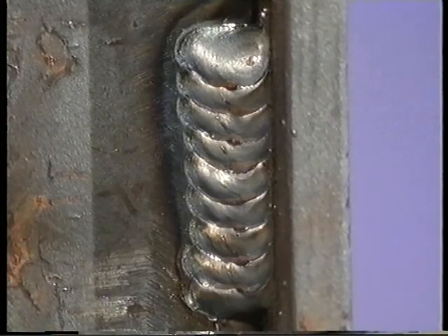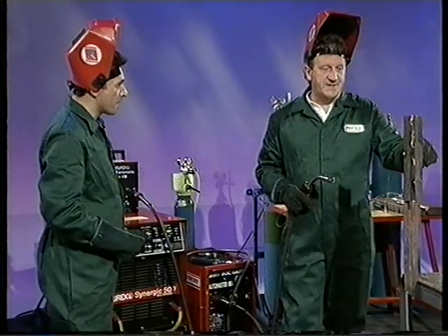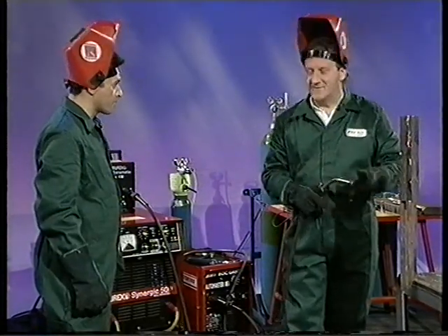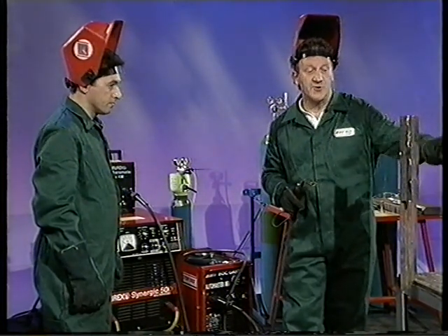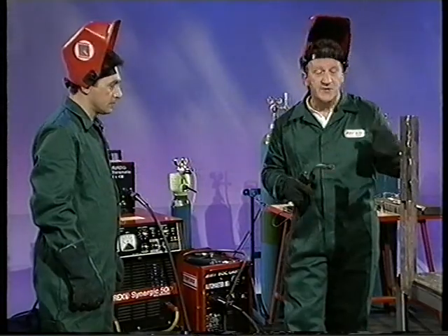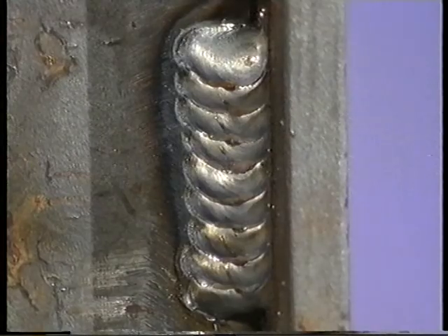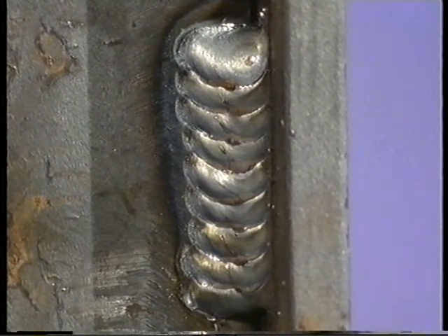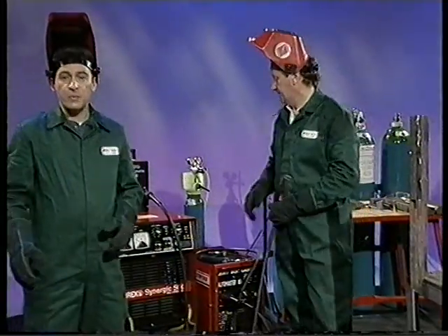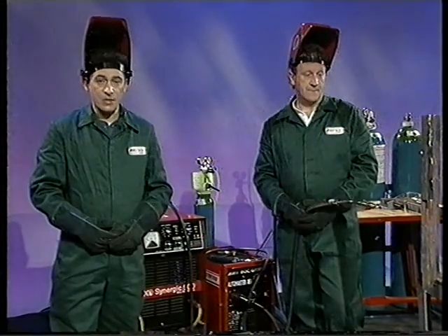Right. Okay, so that's the weld procedure, is it? This is for demonstration only. If we were doing a proper weld procedure, we'd certainly be restraining this by having strong backs on the back. This increases the mechanical strength of the weld. Other ways to increase the mechanical strength are to use flux core wires, for example. Okay, for the moment, Mel, thank you very much. Before we see this process, let's explain flux cored arc welding.